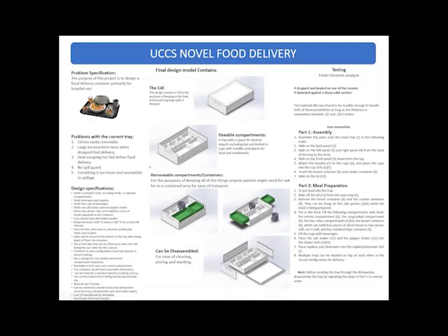Hey, I'm Jonathan Richards. I just want to quickly discuss some of the design specifications and requirements for our product. Some of the more important specifications and requirements include that the tray must be able to fully close to decrease contamination in transit between kitchen and patient. The food must be kept between a specified temperature range throughout the process. The tray in open configuration must have raised sides and rear to decrease chances of spilling up to a given angle, and it must be stackable in both open and closed configurations.